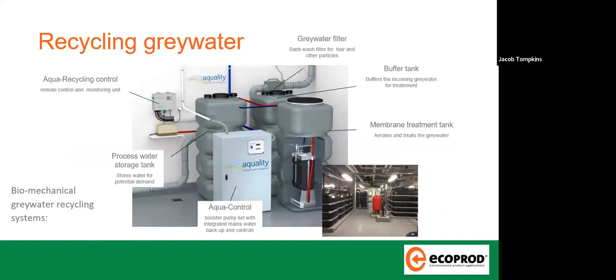And then greywater recycling. There are different types of water. There's blue water, which is effectively rainwater. There's black water, which is the stuff that comes out of the toilet. And there's greywater. That's the stuff from showers, baths, sinks. You need to be careful with sinks sometimes, because if you're in a catering environment and you used it for washing knives that have been used to cut meat, that could be more contaminated than normal greywater. This is why we're here to help you talk through those different options for different systems.